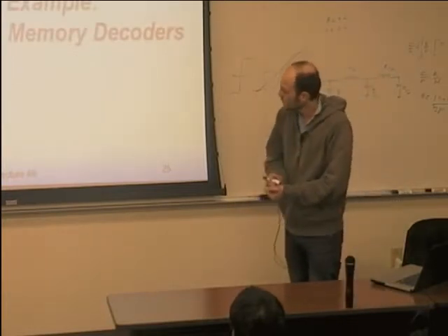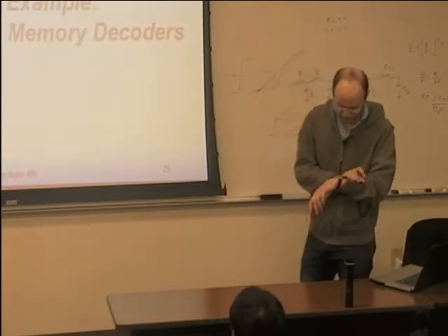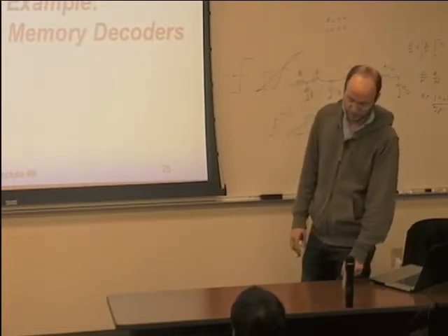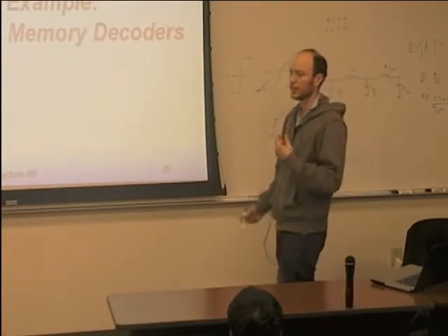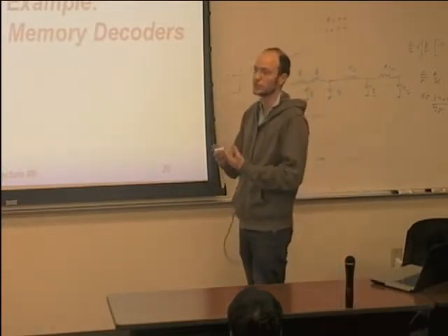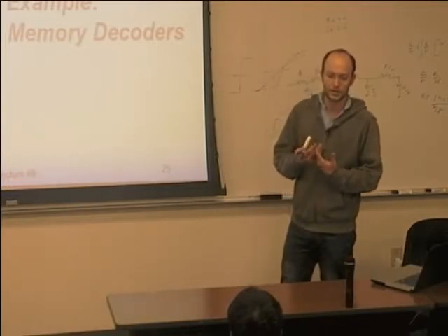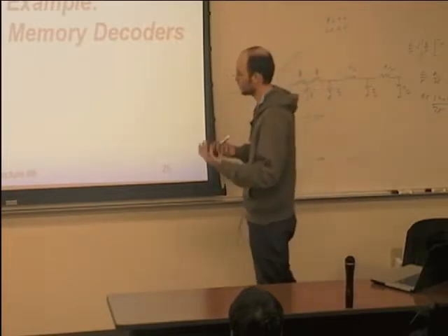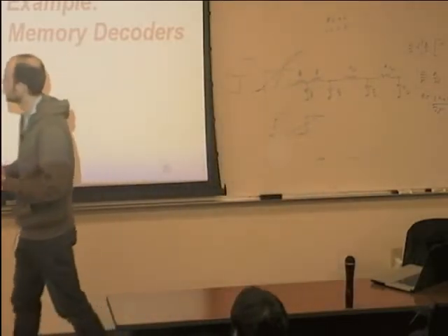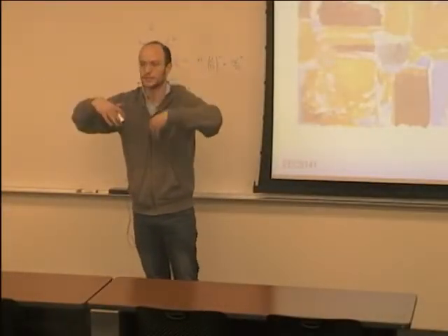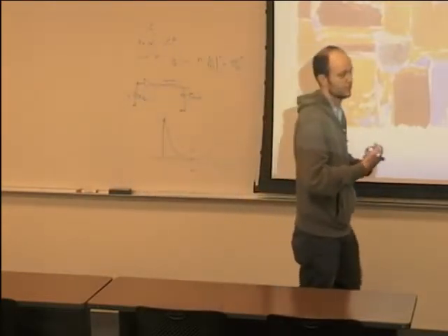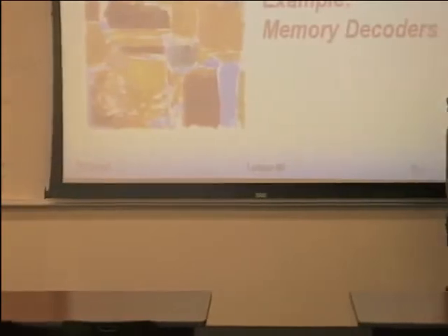Okay. So now, the next thing, which we have like 10 minutes to go over, is decoders. So why are decoders married to wires? Because decoders occur in a memory. Memories are these parts of the chip where you, for example, have cache, L1 cache, L2 cache, so on, that have a lot of transistors, and you need to read out this data. Okay, so then there's very long wires. Okay, so that's why these two things are, we talked about it in the same lecture.